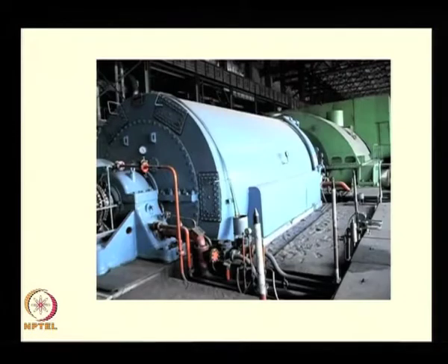In another snapshot, what you see here on one side is the place where the slip rings are, through which the field voltage is conveyed. In fact, the exciter itself is in another room, and the voltage is conveyed to these slip rings via the brushes. At one end you see these green structures; the blue structure here is the synchronous generator itself. The green structures are in fact the turbine, which controls the mechanical power input to the synchronous machine.